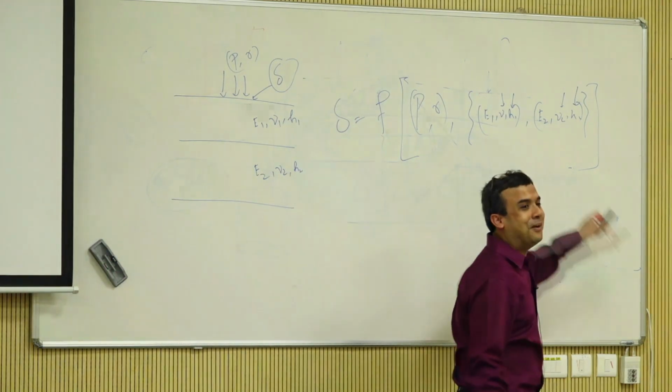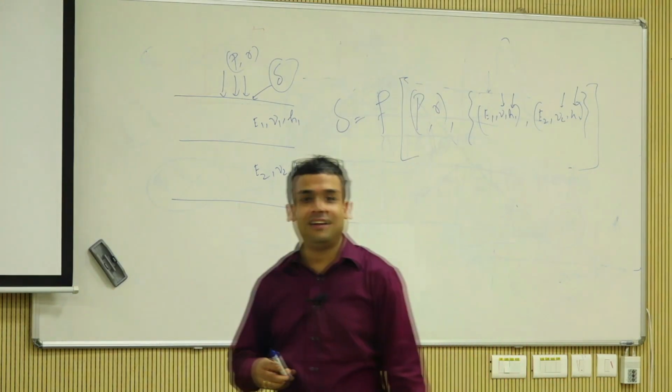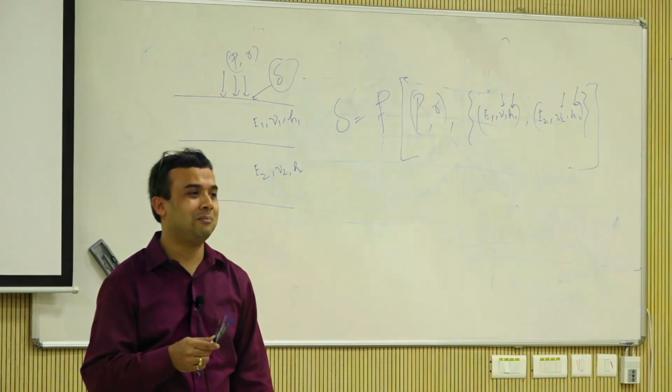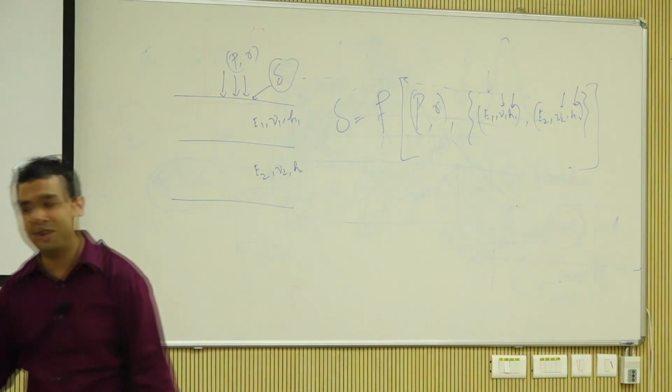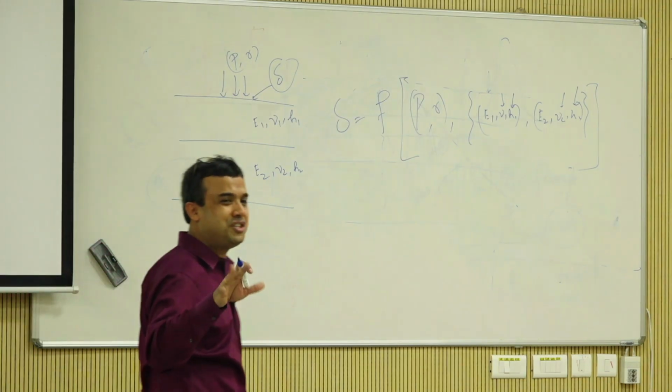I'm not going to make you jump out of the window, but it's 0.5, right? So what is the Poisson's ratio for concrete? No, 0.35 is too high. That's asphalt. 0.15 for concrete, 0.35, 0.3 is close to asphalt. Aggregate is about 0.3, 0.35. Subgrade soil, you usually take 0.4, something like that. So what I'm saying is Poisson's ratio is not very sensitive.